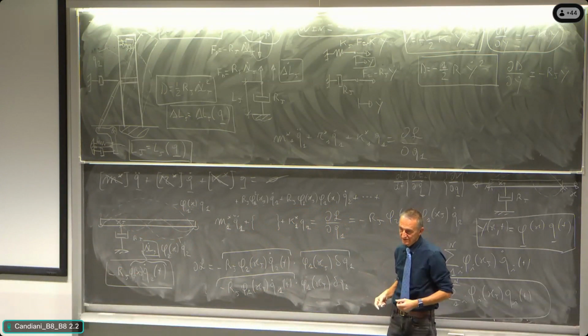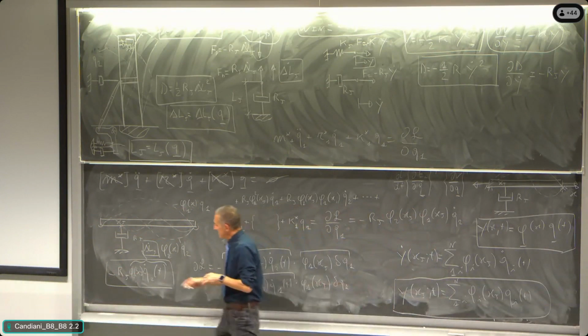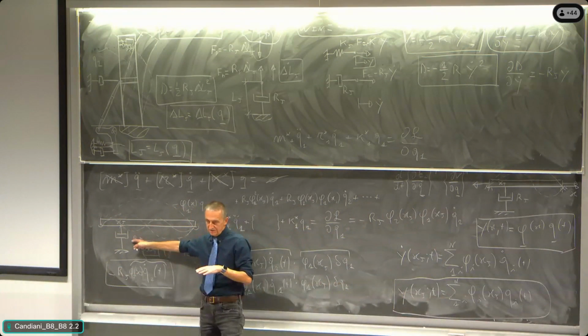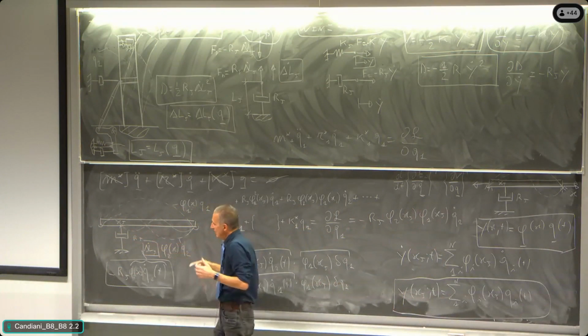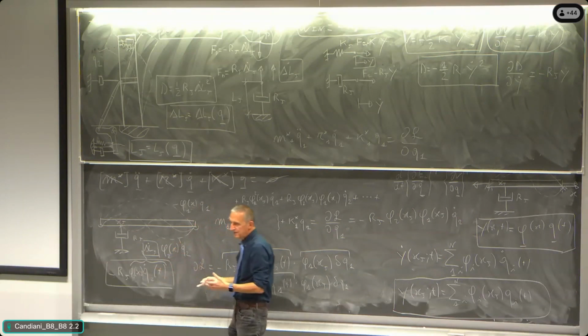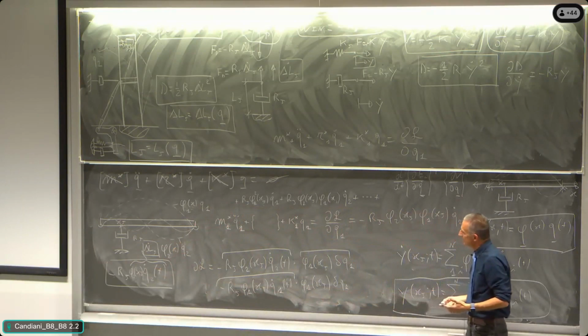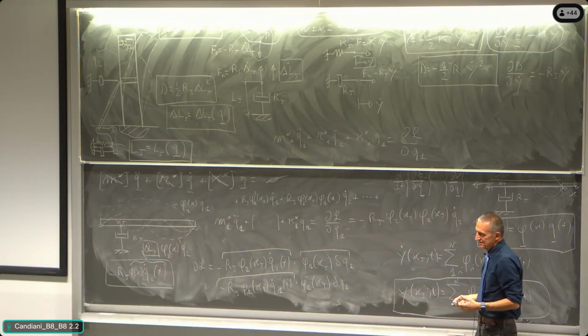Usually it doesn't disappear, all right? And so if we are working with something that is extremely simple, that is the damper, and we apply the theory and we try to figure out what could happen, very surprisingly we find out that the concentrated damper is coupling the modes.